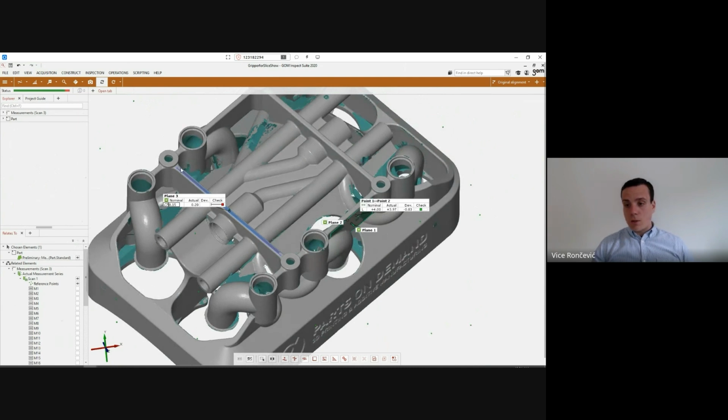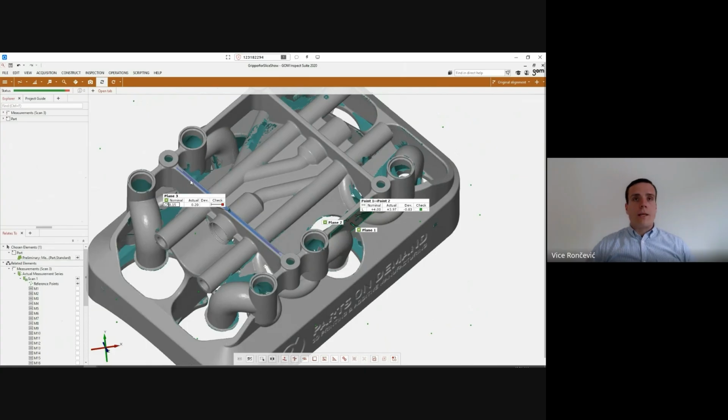In GOM Inspect, you can essentially sample a Gaussian plane at the top. What is a Gaussian plane? It is a plane that has been made by Gaussian fitting. From the collection of randomly sampled points, you want to minimize something called the least squared value. So you assume that the error in this plane is Gaussian distributed, normally distributed.